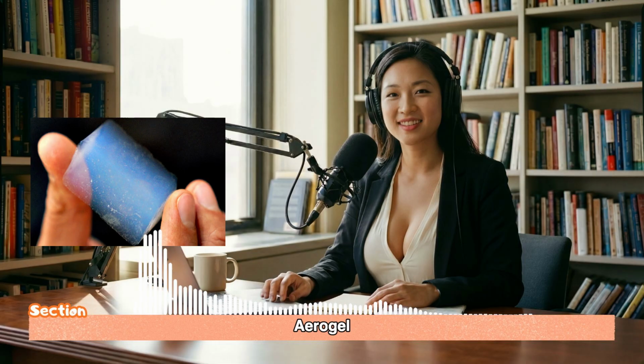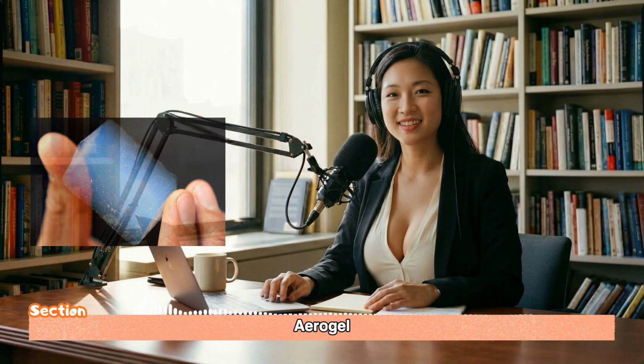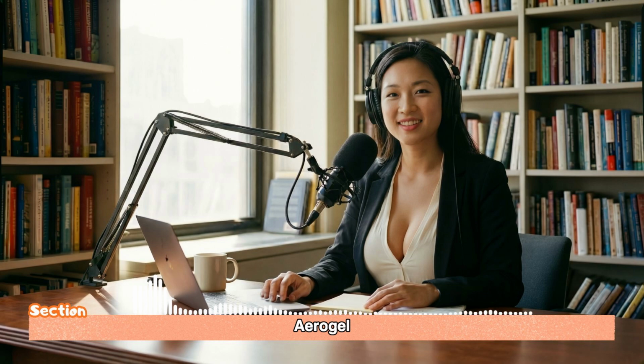Aerogel is genuinely sci-fi material. It's created by removing the liquid from a wet gel through this process called supercritical extraction, which prevents the delicate nanostructure from collapsing. And what you're left with is a material that is 90 to 99% air. It's structured as these tiny silica spheres, just 5 to 10 nanometers in size, forming these extremely sparse, chain-like connections. Its density is remarkably low, and its thermal conductivity can be as low as 0.01.